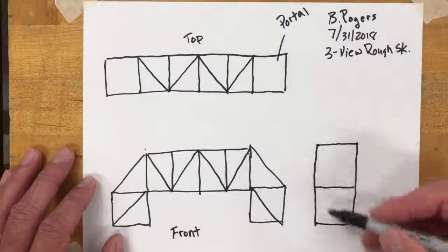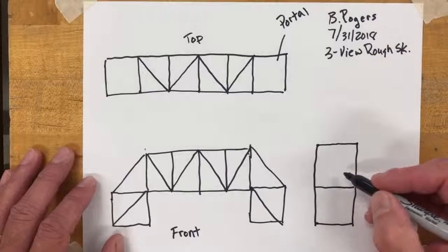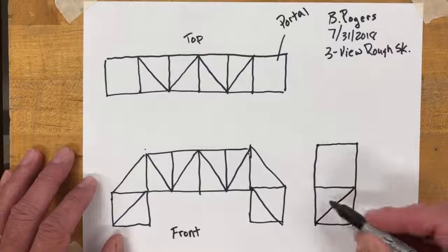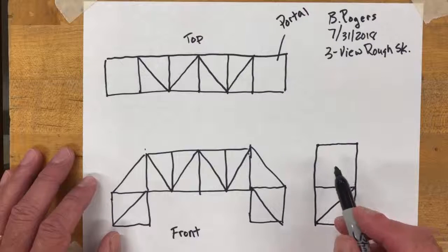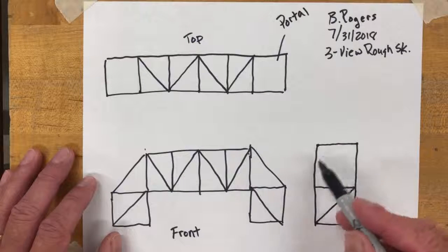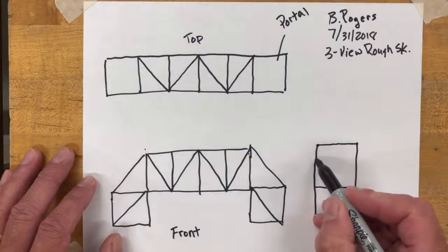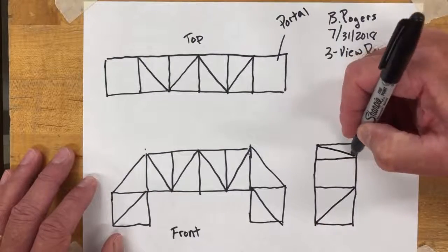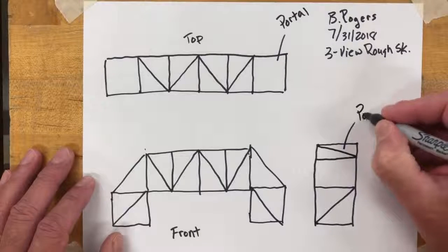Now once again, we've got 2 4-sided figures here. Now this one I've got to keep open because remember that's your portal. This one here I'm going to go ahead and put a diagonal in just to divide that up. Now here's an interesting design note for bridges, especially truss type bridges: we can do something with this 4-sided shape because it is weak. And what we're going to do is create a little portal brace in here. So I'm going to put a rectangle in there, and then I'm going to put a diagonal in there. And this is what we're going to call the portal brace.